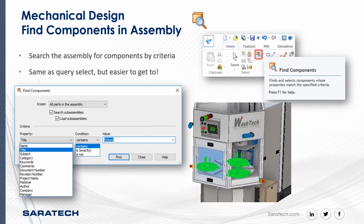Next, we get into our assemblies. So, find components in assembly. This is a big one that a lot of people were asking for. Hey, I'm looking for a part, so now I can do a find component. So you can see up above, here's my icon. If I put my cursor right on top of it, it tells me it finds and selects components whose properties match the specified criteria.